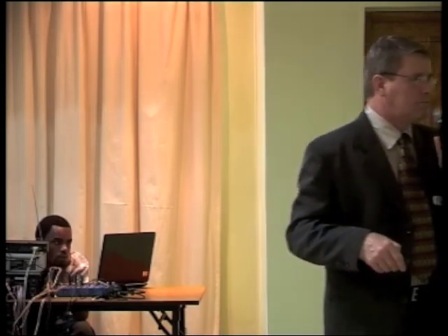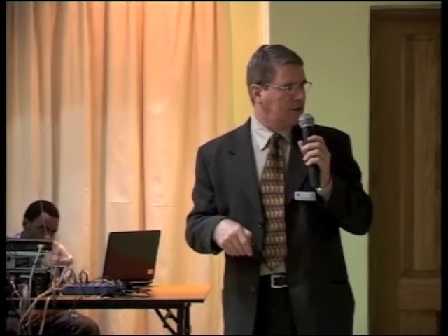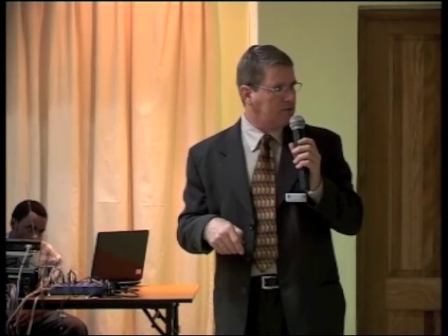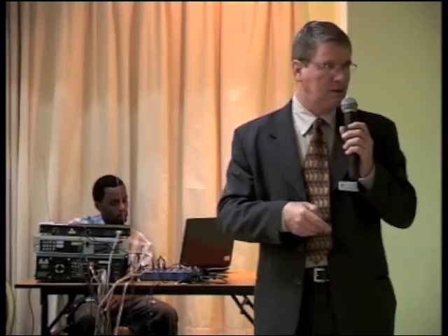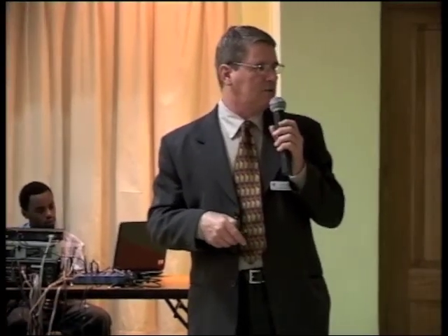And when we consider tension, these are the main elements. But when we consider bending, it's important to look carefully at these points where the cable changes direction. Then it's important to have guides, special mechanical guides, just to give the radius of curvature that we expect to be higher than the limit of the cable.